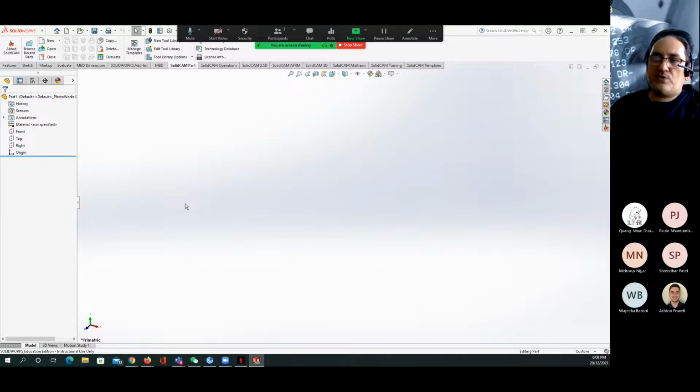So as you remember, we said that when you take a look at the part, the right side is going to be the x-axis, the upper axis is going to be the y-axis, and the depth is going to be the z-axis. So where can we find such coordinates in SolidWorks? Take a look at this thing here. You can see my mouse, because usually I have problems that students cannot see my mouse when I share the screen. But anyway, at the X, Y, Z here, we can see that the Z is the blue one, the Y is the green, and the X is the red.